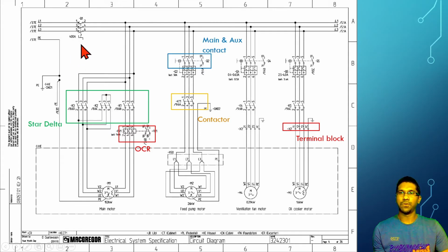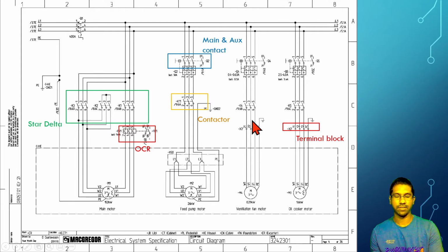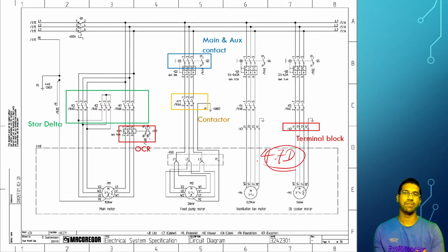Suppose you want to mention this terminal block. Its coordinates are page number 4, so 4.7C or 7D. Let's say it is more or less under D. So it will be on page number 4, then it will refer 4 point then 7D. The notation will be like this.